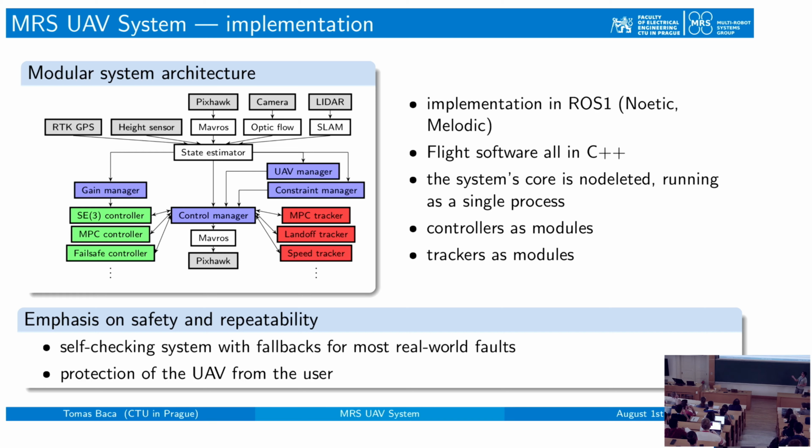Then we have a plugin which encapsulates everything regarding feedback control and reference generation. And this plugin makes sure that the drone uses the right controller at the right time. And it's very useful when developing new controllers. So if you as a user would like to test your own feedback control, some model predictive control, for example, you can add your controller in here as an additional controller.